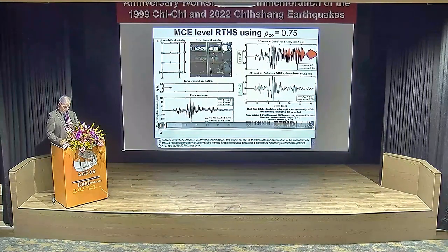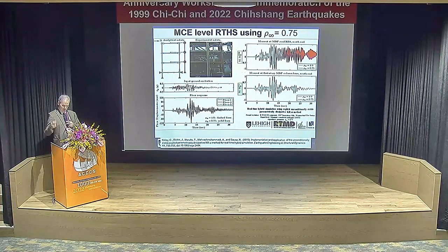You can hear this is the actual test, and you'll see here as the integration develops, the red is that previous solution, the blue is now the overlay with the dissipative characteristics, and it doesn't destroy the modes of interest. Right, here's some animation here, and it gets rid of that high frequency noise. So of course you've got to be careful, because if you specify too high a value of rho infinity, it starts to deteriorate the lower modes that you're interested in, and you could overdamp the system. So you have to be careful about this.